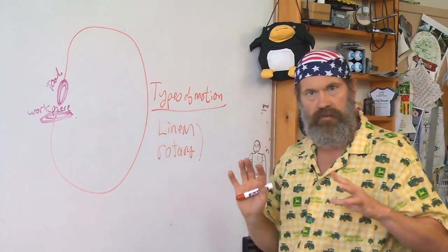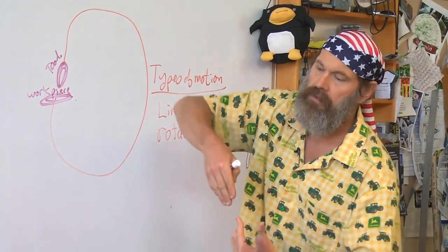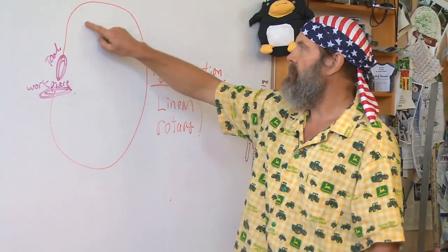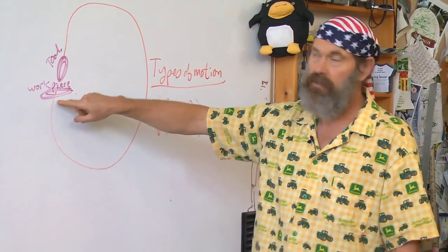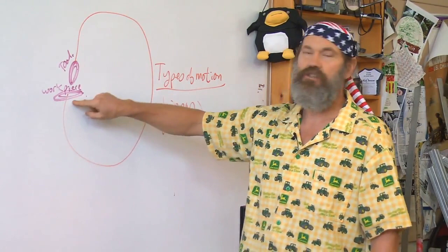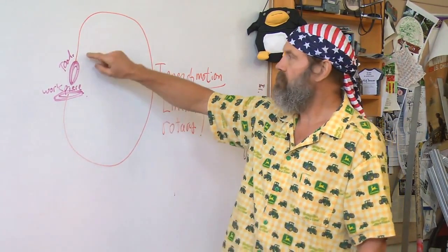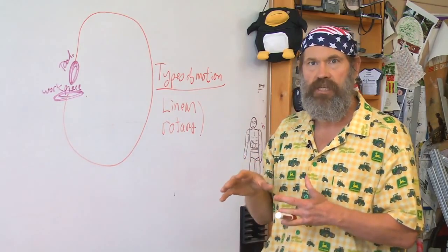Because remember from your knowledge of a structural loop, as the machine moves, you would like the shape of the structural loop to remain as constant as possible. You would like the length of the structural loop to be as small as possible. The smaller the structural loop is, the greater the potential stiffness of the machine.